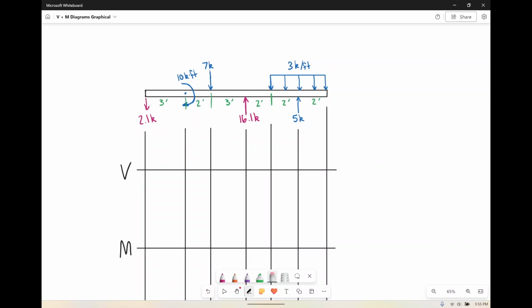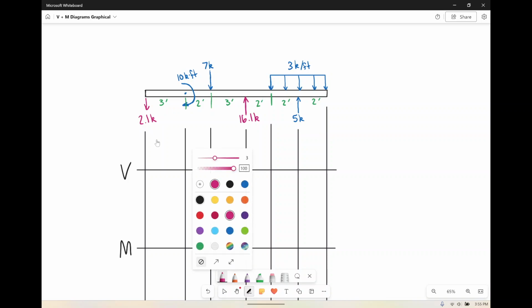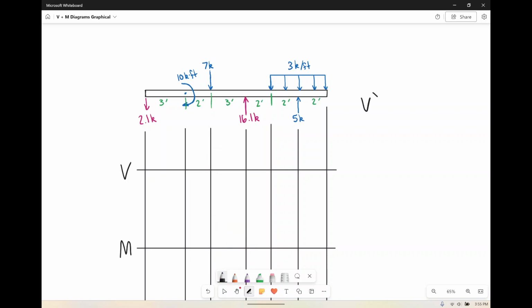Now that we have figured out our reaction forces, we're going to start by solving for shear. Shear is first. You can't do the moment diagram unless you have shear, because if you recall for shear moment diagrams, the load diagram determines the shear diagram, and the shear diagram effectively determines the moment diagram. There are lots of little bits and pieces that go along with that, with calculus and all that, but just to sum it down into some baby things.